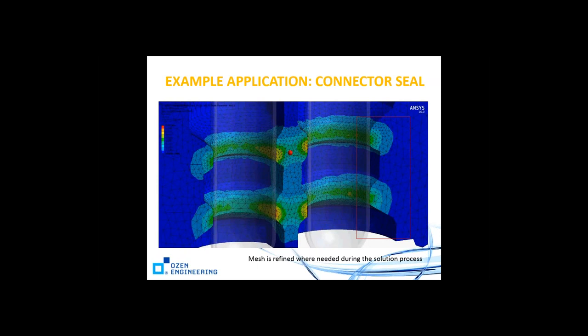This is still quasi-static, but there are multiple load steps, so it's quasi-static but close to transient. Yes, this would be sort of like an elastomer, like an O-ring. But can't you just run that as a hyperelastic material? Yes. This material can be hyperelastic, elastic, plastic. You can specify any type of material. If it is deforming to the level shown here, then it's going to be hyperelastic, right?